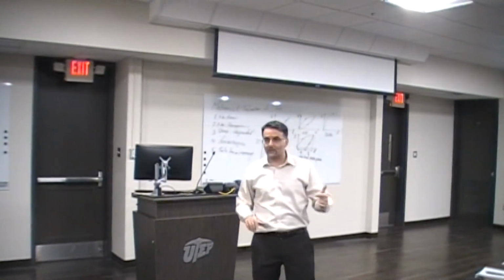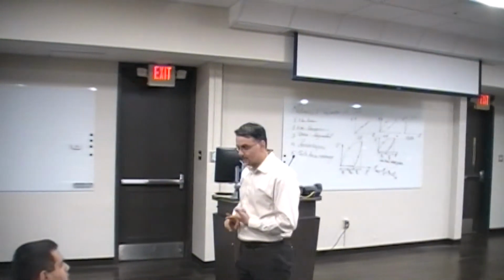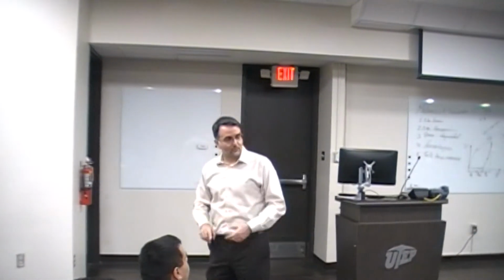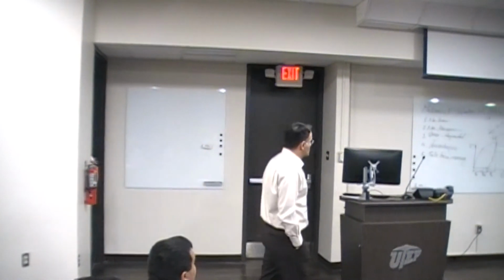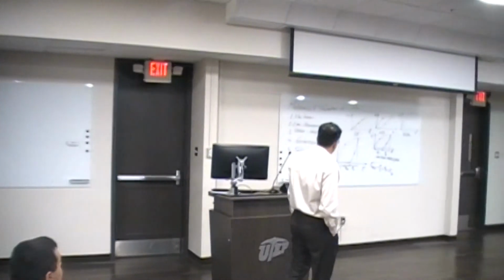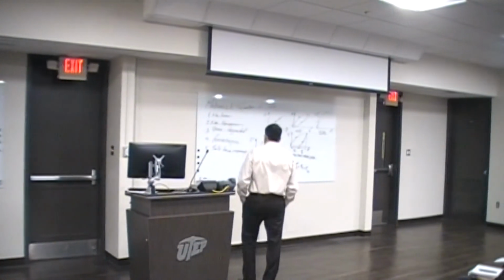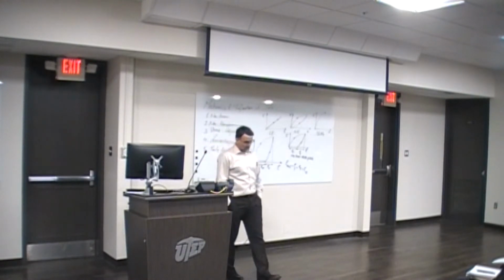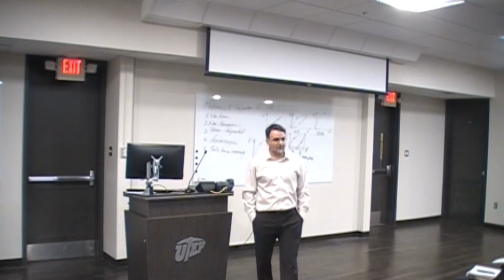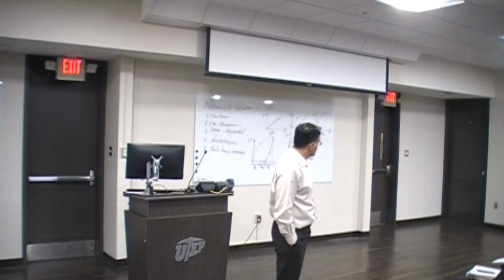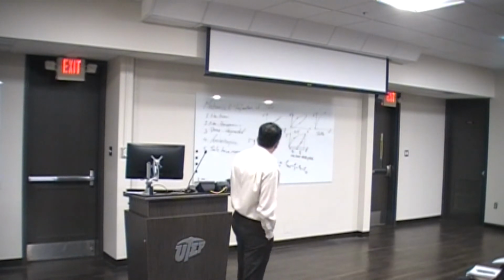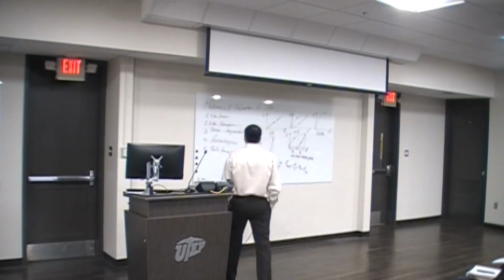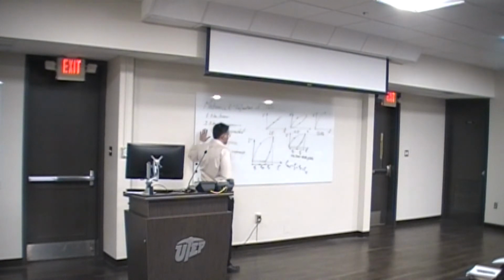Concrete doesn't have this component. Asphalt doesn't have that. Wood doesn't have this. But soils do have memory, and we have tests, and you're going to see those tests, and hopefully run them in the lab to be able to find the pre-compression pressure or the maximum past pressure of the soil. So these are typically what we have to talk about in terms of the general mechanical properties of the soil.